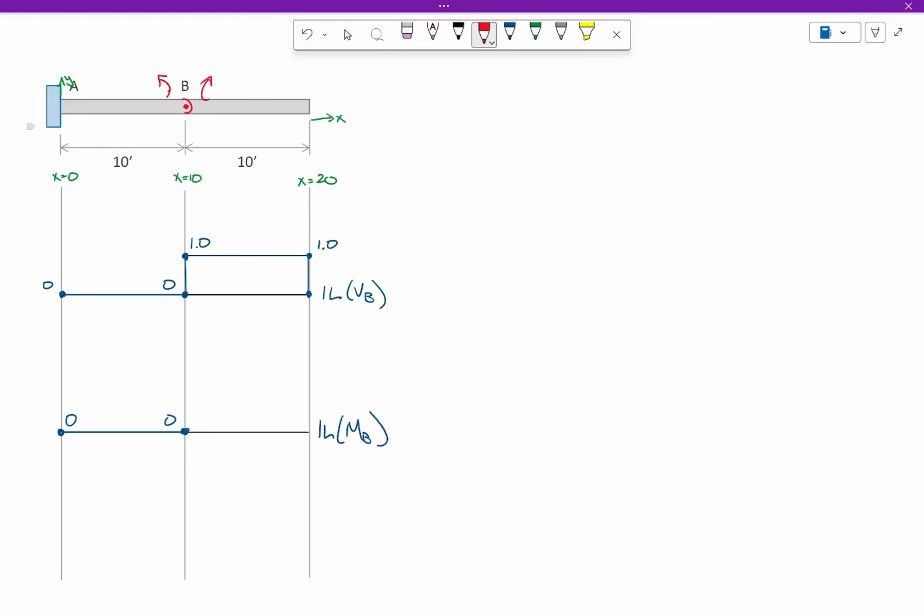So, what does our influence line for moment at B look like? It looks like that. Why am I drawing it downward as opposed to upward? Because the diving board makes a frowny face. Okay? It's a negative bending moment diagram. If I were to plot the bending moment diagram for the load over there, the moment diagram will be negative across the board.